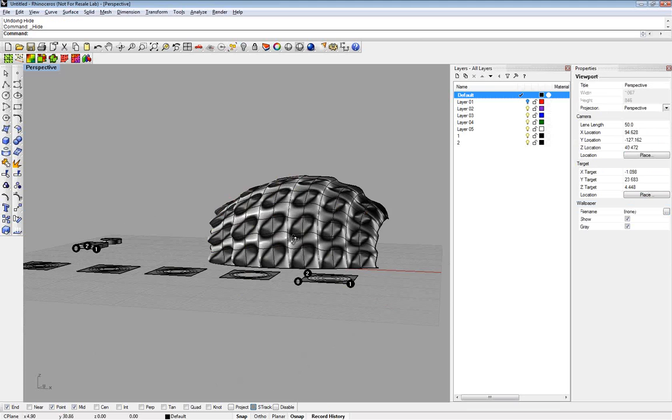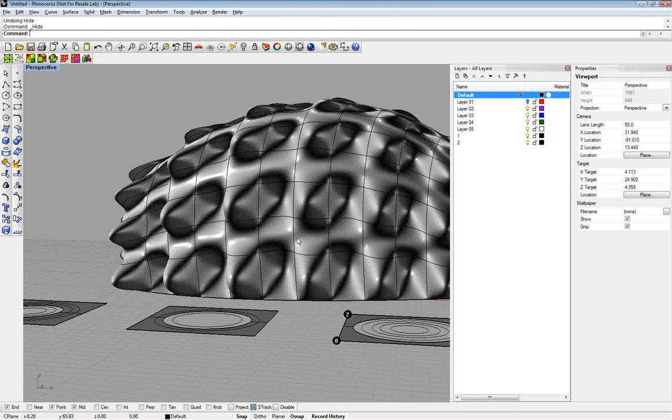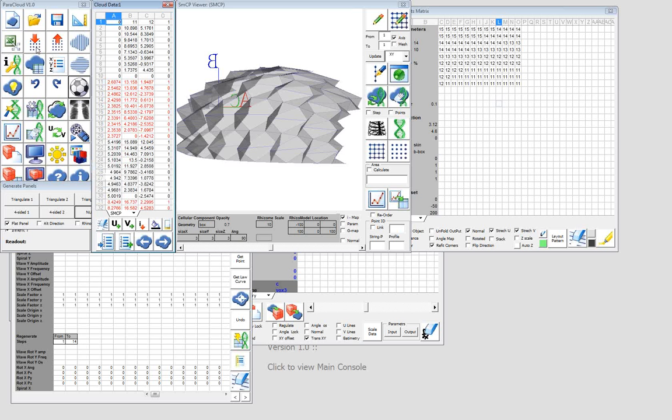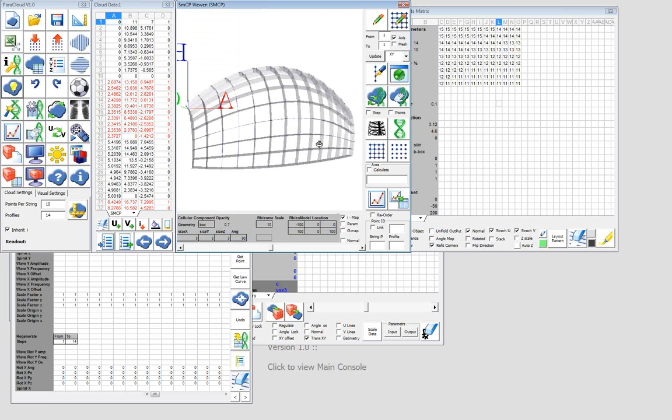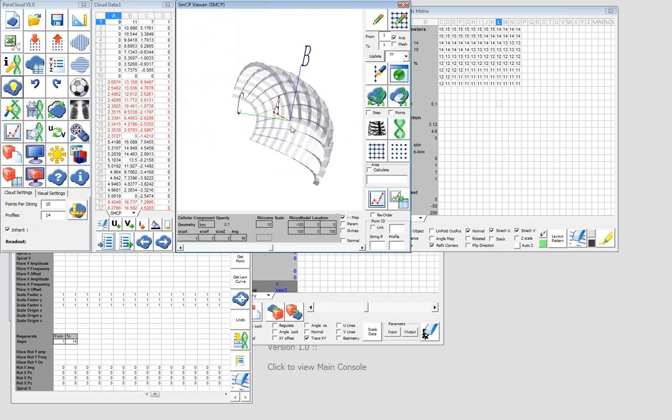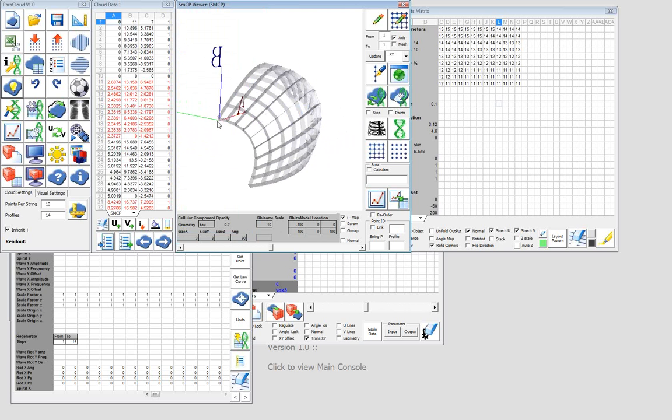Now, once we have the geometry in, we can also control the way that it behaves as a rib system by providing an offset to it. So I'm going to provide an offset of 1 unit just to see as a starting point how it works. So you can see that my geometry was now converted to a rib system. The rib system starts from the first point here and projected outwards normal to the surface.